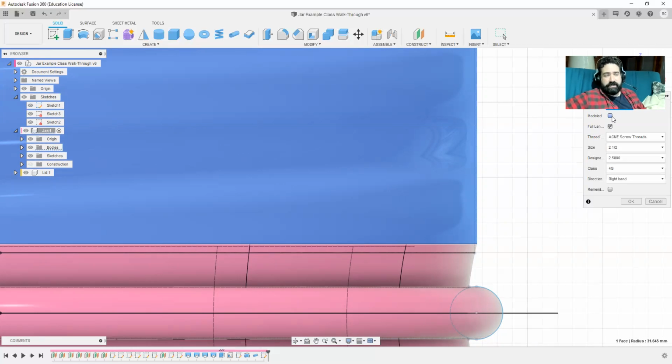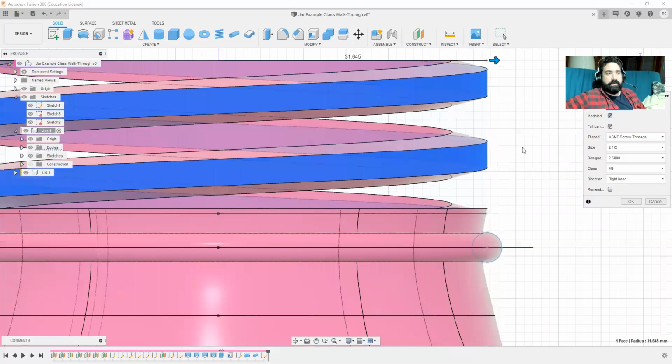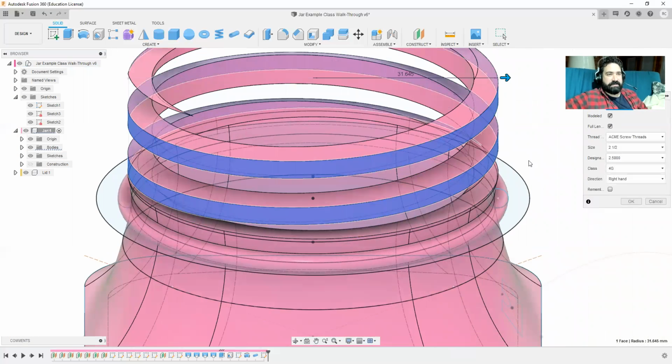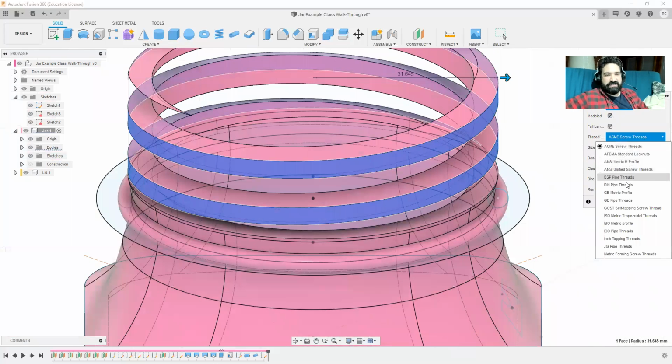And if you tried to export this model for 3D printing, for CNC manufacture, whatever, it will remember that. But just to save a little bit of power when it's modeling, it will not fully render that, fully model that in your file. But if you check that checkbox, now it will fully model that. And then you can see the real problems that come from some of these things. So that's why I say, just probably leave it at its standard.